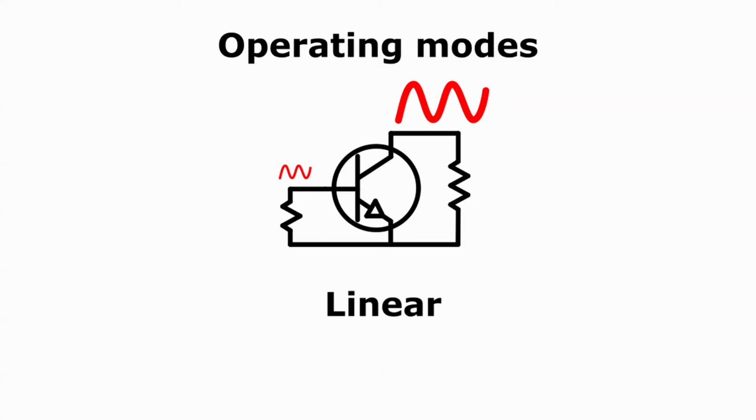If the circuit works well, then the output signal will be a scaled-up version of the input. If the output is distorted in some way, then the amplification was nonlinear. Usually, a designer wants the scaling up to be linear, so that the output looks the same as the input, just bigger. The green arrow shows the main path taken by current flowing through the transistor when it's operating in linear mode. The input signal will add a bit of current, but the overwhelming majority of the current will flow in at the top and out at the bottom.